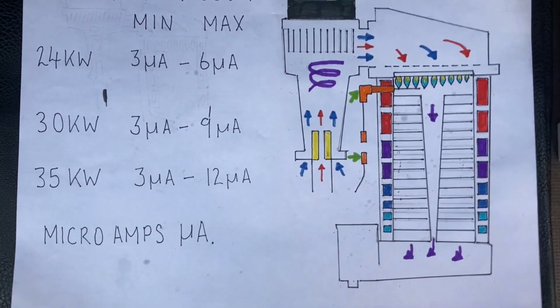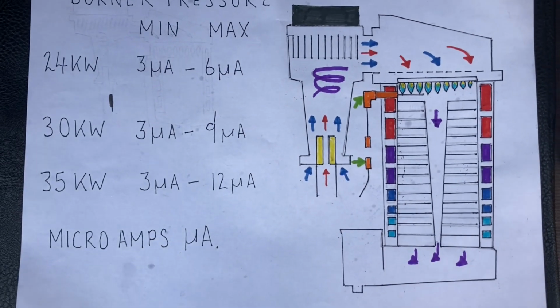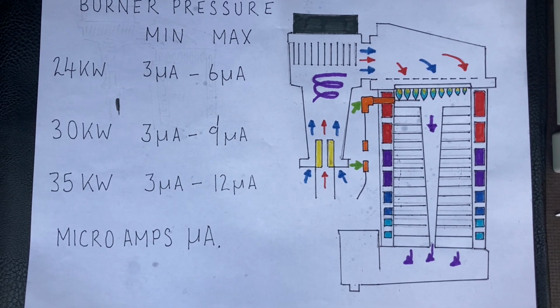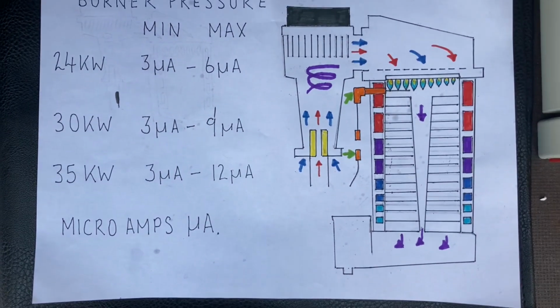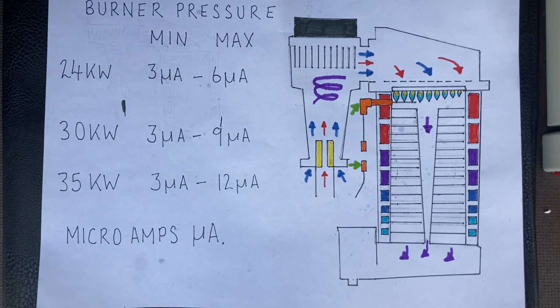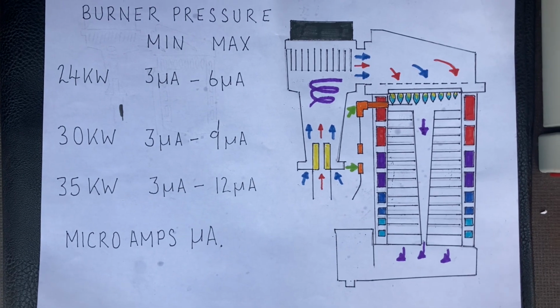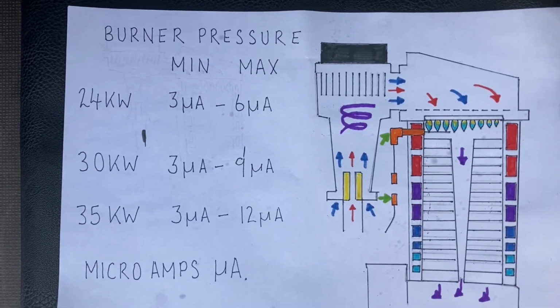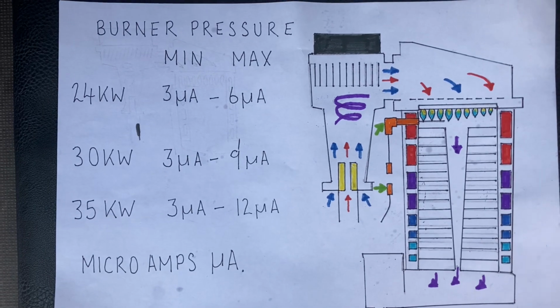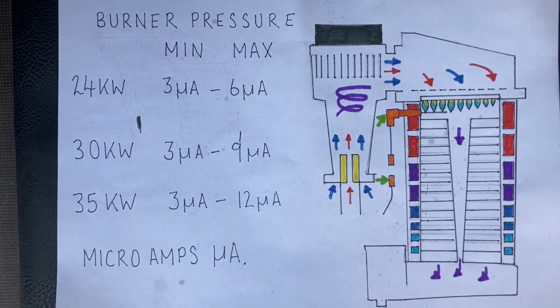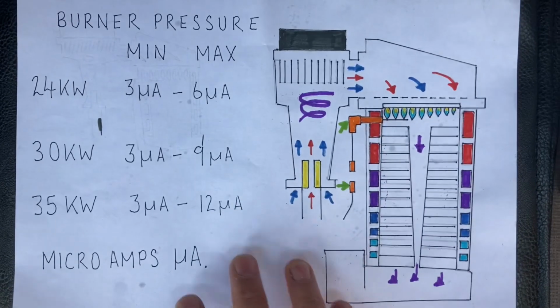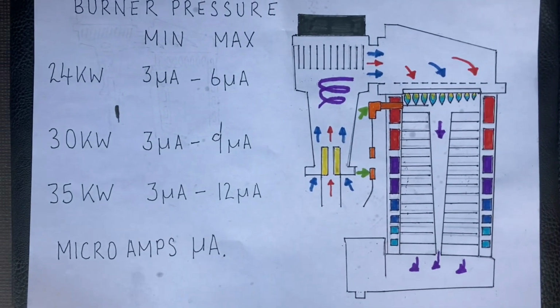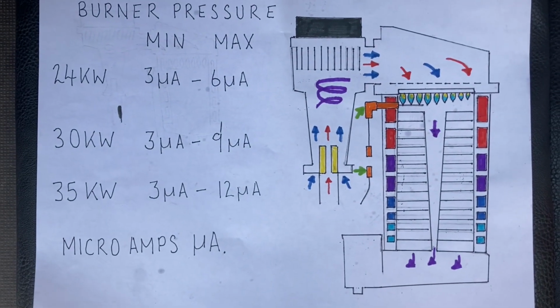when I've come across this problem before, when you're getting poor hot water, 9 times out of 10, you'll probably find a plate heat exchanger is blocked, or the pump's slow, or the thermistors are out. But if they're not, this is where you should be looking. So I thought I'd bring this to your attention, and it might help somebody, because this is a problem I figured out by myself, and it does work because I've done it.